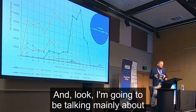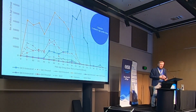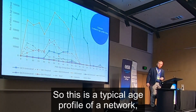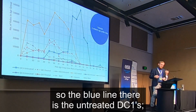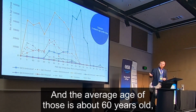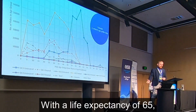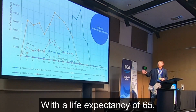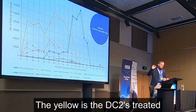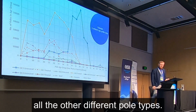And look, I'm going to be talking mainly about wood poles here. It is applicable to steel and concrete as well. So this is a typical age profile of a network. The blue line there is the untreated DC1s, so durability class 1 timbers, and the average age of those is about 60 years old, or 50 odd years old, in that network. With an average life expectancy of 65, that's a fair chunk of the network. The yellow is the DC2s treated, and everything else is scattered amongst all the other different pole types.